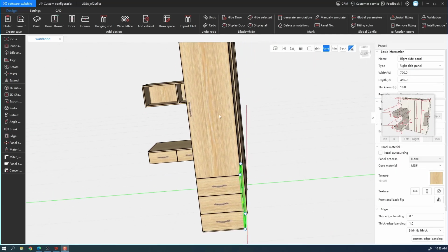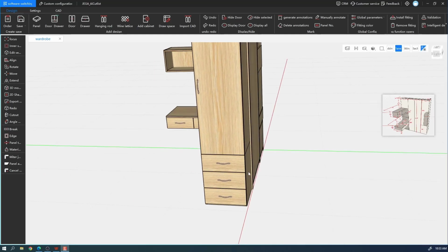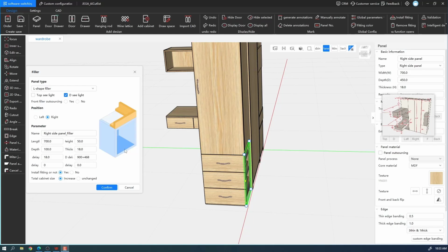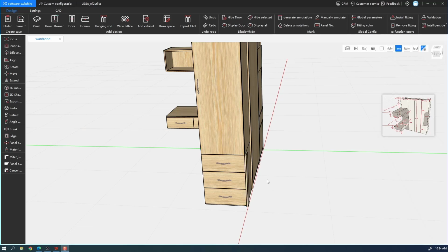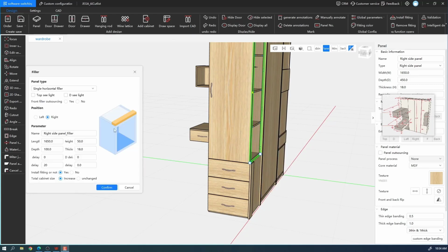You just rotate to the right side as front view and just right click on it, add filler. Come here to select the filler styles. Here you only want it to be like this type, and I don't need this one now. Here going down to select the height. This one to delete, this here to be 0. And I want it to cover the door, so I still input 20 and hit generate. Then it will be like this type. Still the top, add filler.